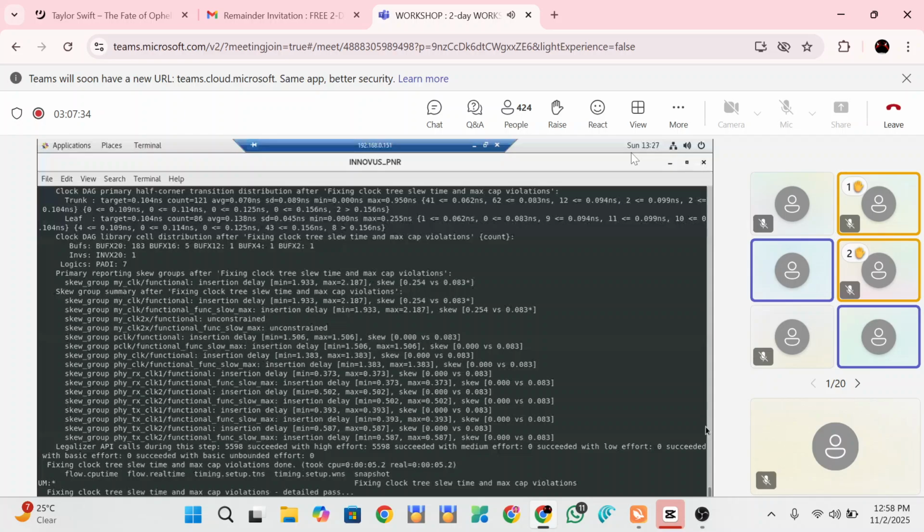Now we are connecting each and every standard cell and input and output properly. In real, the same thing will be printed or manufactured or fabricated on the wafer. Okay, this is how it is, to show us visually how we are doing that. Different metal layers are using a number of directions. One layer will be routed horizontally, one will be routed vertically. Then there's the other. Let's see.